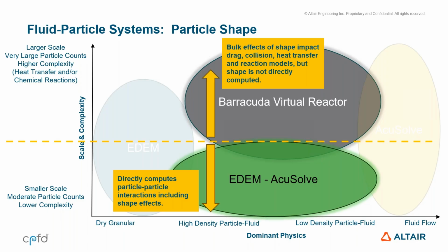And systems like we just talked about, the combine harvester, you have both the areas where it's much more dilute, where the hydrodynamics is dominant, but also locations where you have a particle bed that kind of forms on the sieve and chaffer, right? And there, computing the particle-particle interaction is really important for determining how closely the particles can be packed. So it's really critical to this whole solution.